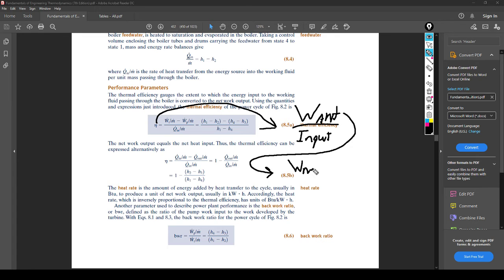So this breaks down to the following. Work net. And we use work net because we're taking into account those other questions we had, where the power cycle develops this, this is the heat leaving, this is the heat in. It never said that there was any work being taken. We didn't have to add any work to the system in those questions. But in actual power cycles you do, because there's a pump, and probably a couple of them at least. So work net over Q in.